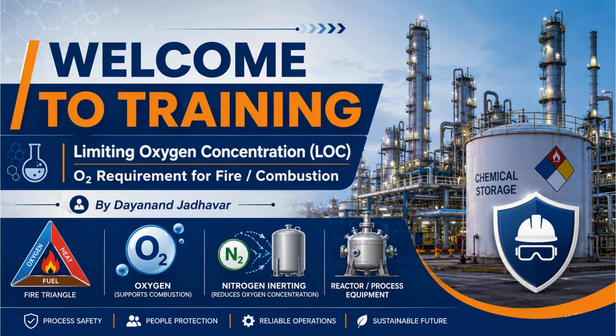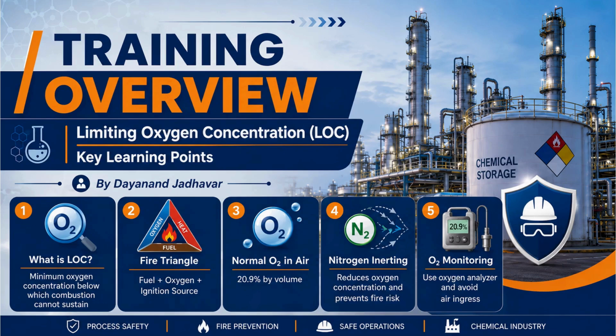Welcome to this training on limiting oxygen concentration, commonly called LOC, and oxygen requirement for fire and combustion. In chemical plants, we handle many flammable solvents, vapors, gases, dusts, and oils. So understanding oxygen control is very important for fire and explosion prevention. LOC means the minimum oxygen concentration below which combustion cannot be sustained.